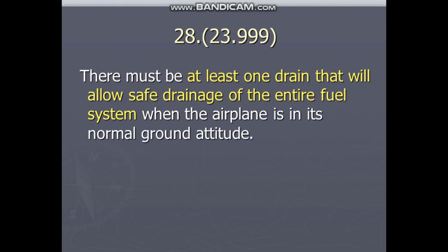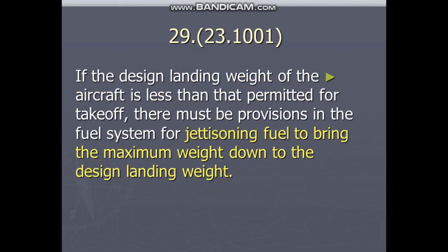28. There must be at least one drain that will allow safe drainage of the entire fuel system when the airplane is in its normal ground attitude. 29.